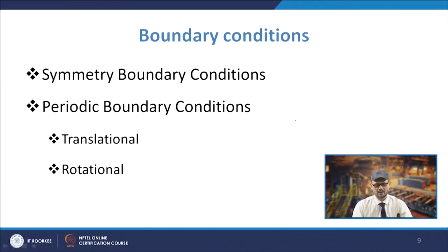Then once you have put these boundary conditions, you need to ensure what other things you need to know, like you have to specify the material properties. In fact, the material properties are specified before we apply the boundary conditions in many CFD tools.